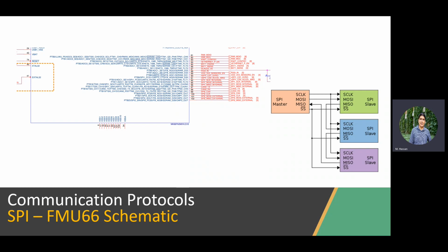In fact, if I remember correctly, FMU has 2 SPI connections, so you can identify SPI 1 and SPI 2 4 wires that are coming out of your system on a chip. Good. If you don't see, you have to trust me, those are the lowest wires on the right side.